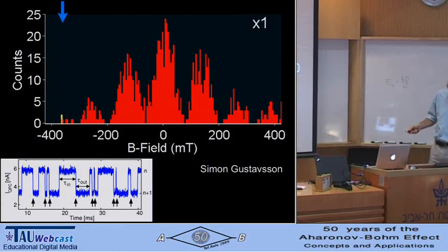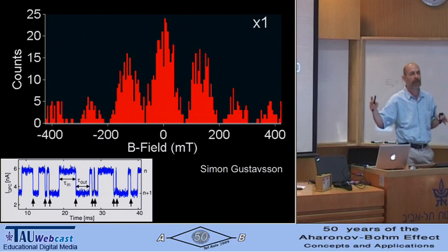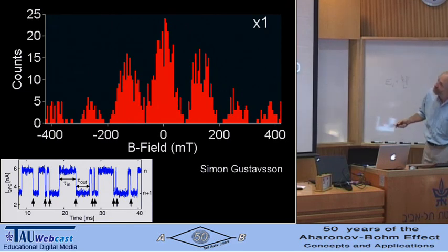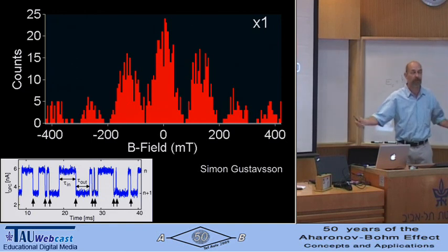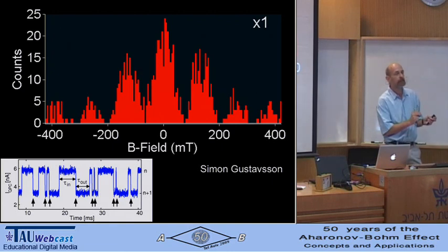So this is our detector current. The detector current fluctuates between two values. The two values correspond to electron in, out of the double dot device. And if you simply count the downturns, each downturn means one electron has been effectively transported through the double dot device. This gives you a count rate, which is the vertical axis here. And you see very nicely that you can do an experiment pretty much in the same way as you can do it for individual electrons in vacuum.